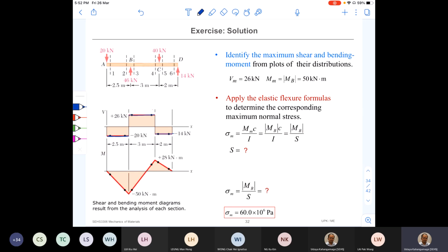So I have done it here. I just want to show you how I did the construction here. So at point A, when x equals 0, bending moment is 0, right? MA is equal to 0, no bending moment. I got 1 point. And then the variation of bending moment between B and A is given by this area.